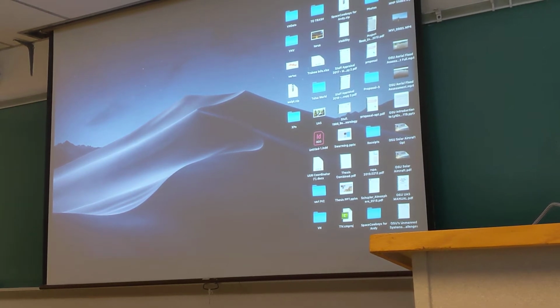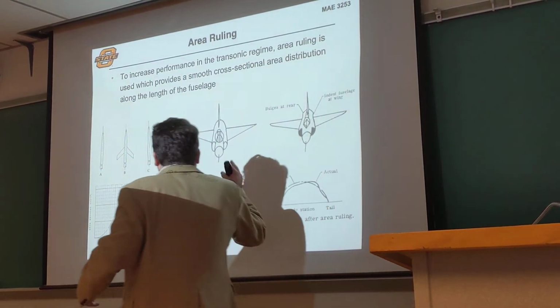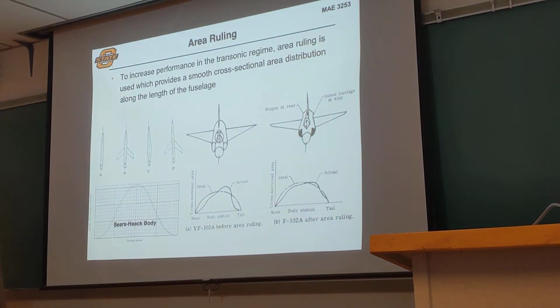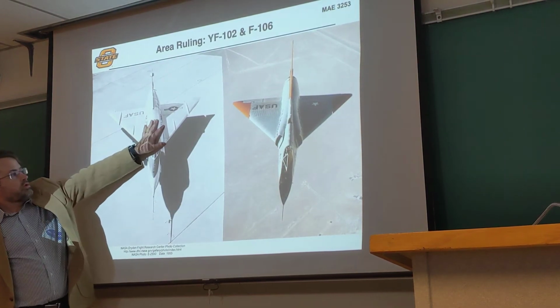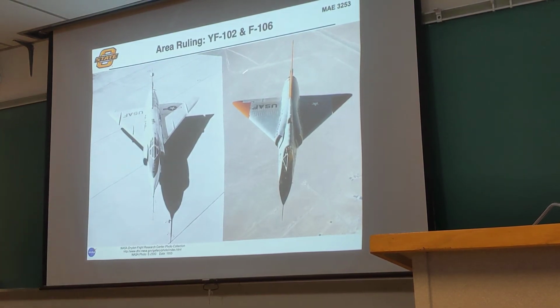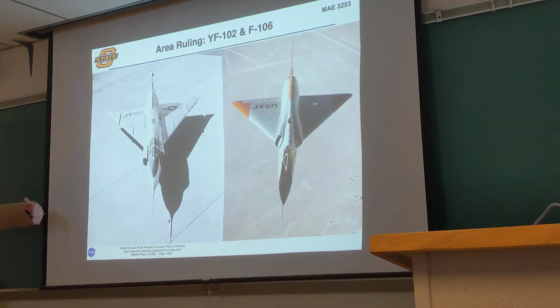And we were discussing area ruling. Remind ourselves about the basic concept here: we're going to essentially streamline the cross-sectional distribution of the aircraft as we're moving from the nose all the way to the aft section, so tip to tail in this case. So rather than having our nice circular fuselage here, we're going to contour this thing and essentially neck it down. As we're increasing the cross-sectional area by adding a wing onto the fuselage, we're going to reduce that fuselage and basically give it this waist.